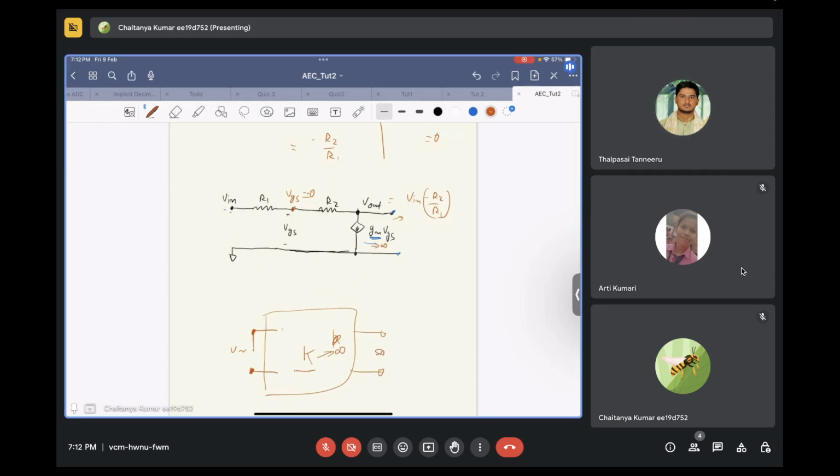But I am saying that this particular circuit is connected in negative feedback. If the circuit is connected in negative feedback, it can't give you infinite output, right? Because the system has to be stable. Yes, sir. It can't go beyond plus VSS, minus VSS. It will give you something that is linearly dependent on the input. It cannot go unstable. It cannot give you infinite output. So negative feedback will behave in such a way that the input of whatever this controlled source is goes to zero.